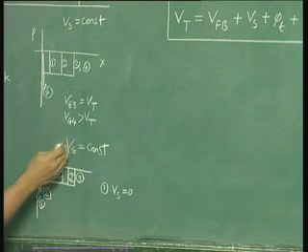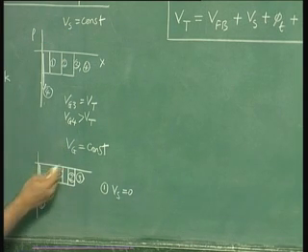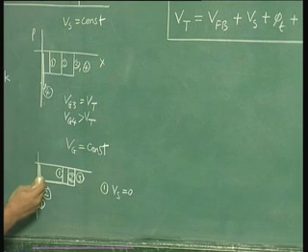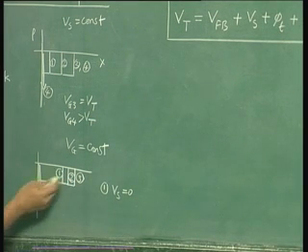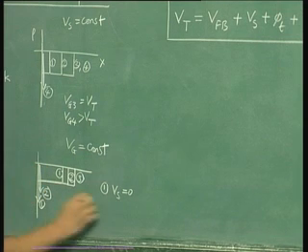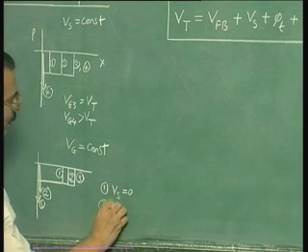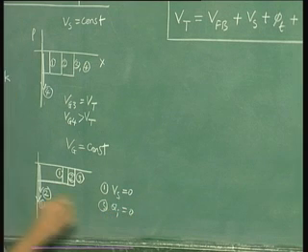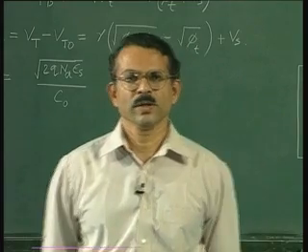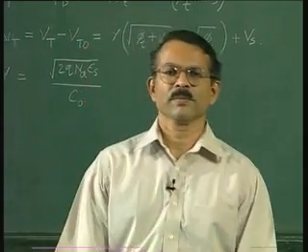So here when you keep Vg constant and you go on increasing your Vs, your depletion region expands and inversion charge goes on falling. For 3, inversion charge is equal to 0. So we are not showing 3 here, and this is a threshold condition. So in summary, that is the body effect.